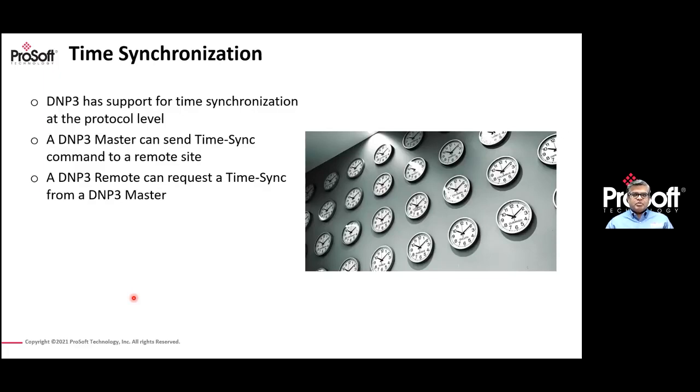And the nice thing with DNP3 is it supports that at a protocol level, so you don't need an additional device, or you don't need additional logic to create that. You can handle it at the protocol level as well. And with DNP3, the master can send in that time sync command on a regular basis to make sure the remote sites are all time synced. But at the same time, a remote site can also request to say, just make sure that my clock is synced, so all of my logs are accurate to the right time and so forth.